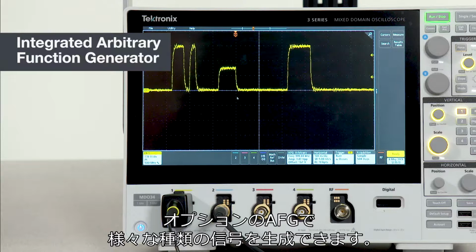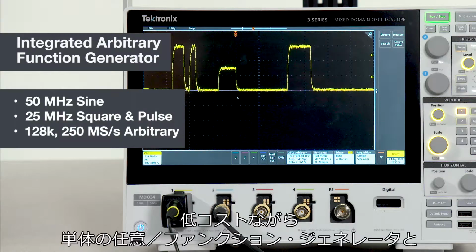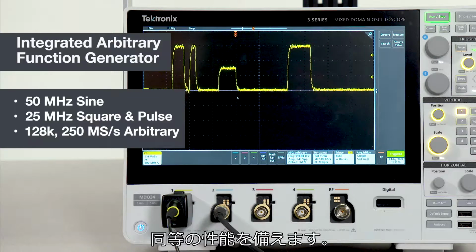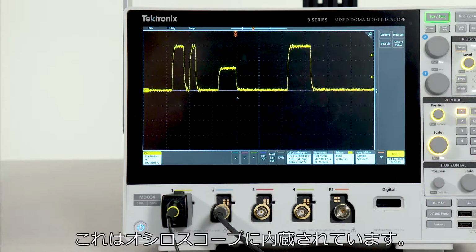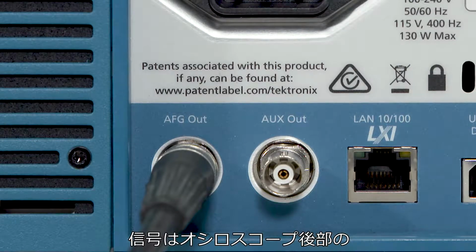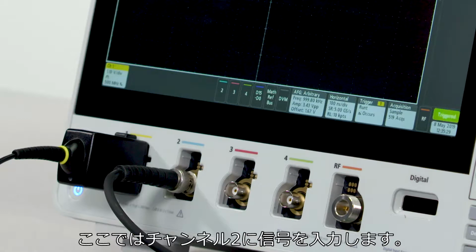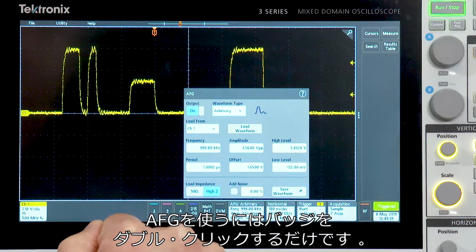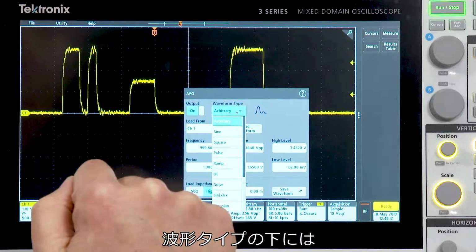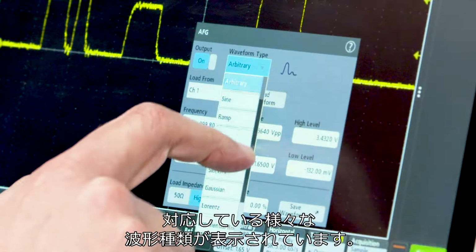The optional AFG can generate a wide variety of signal types and has performance comparable to a standalone function generator at a fraction of the cost, and it's built right into the scope. Signals are delivered through the 50 ohm output on the rear of the scope, and in this case, we're routing it to channel 2. To use the AFG, simply double tap on its badge. As you can see up here under waveform type, there's a wide variety of waveform types we support.